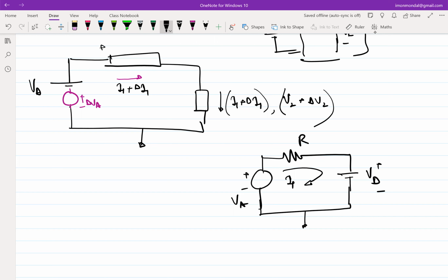It's almost like a black box. The current-voltage relationship for that element is a black box for the rest of the circuit. If I can retain that, then I can replace it with anything, as long as the rest of the circuit isn't bothered, because it only interacts with that element through the current-voltage relationship. Okay, so that is essentially a storytelling version of the proof, but obviously you can do a rigorous proof.